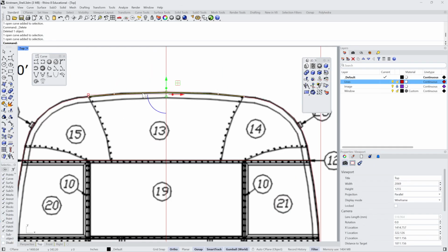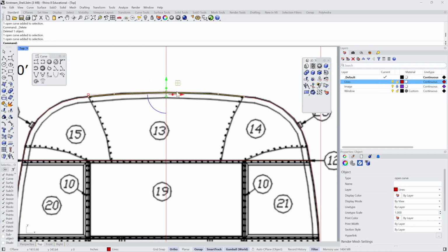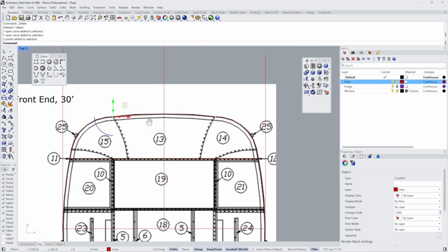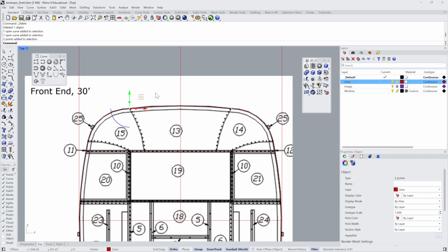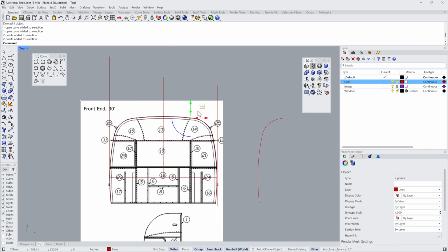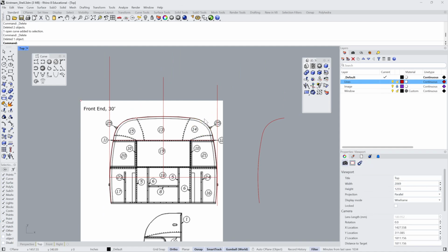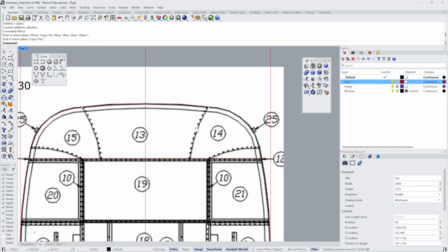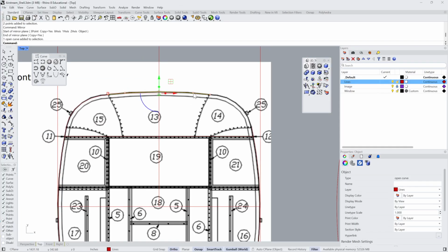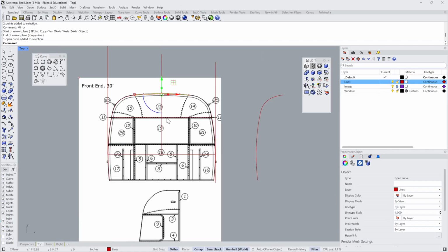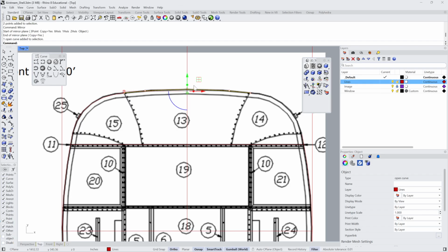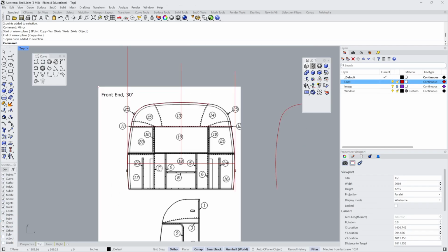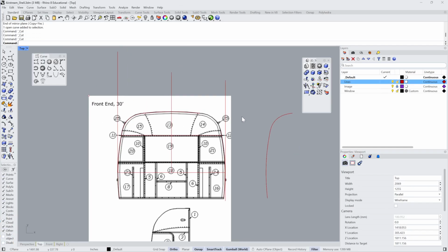you want this curve to go across the middle of the thing. So the trick to that is just to put a point. To establish your center line, put your point on one side, and delete the point over here and all this stuff. And I basically just mirrored this point, and that way I knew where to put it so that everything would be symmetrical on both sides. So then I'm drawing this line between those two sides, and then I'm just constructing one side and then mirroring it on the other side.